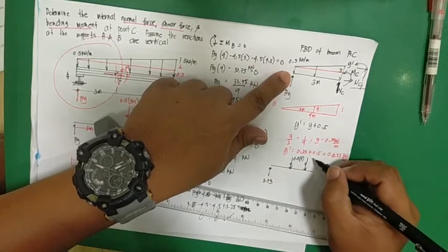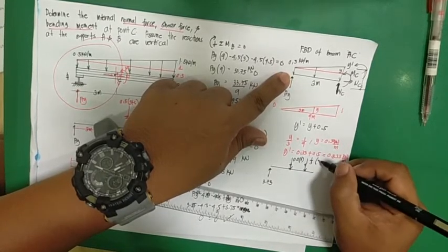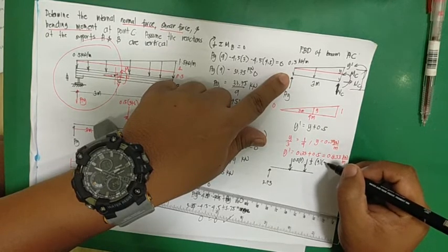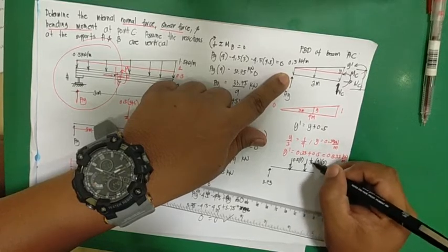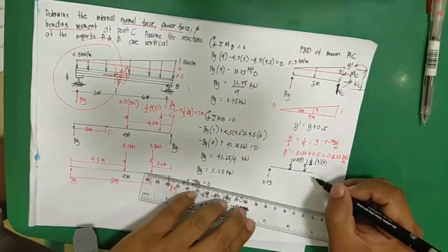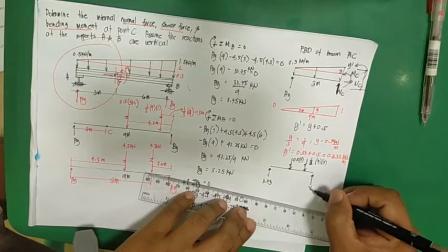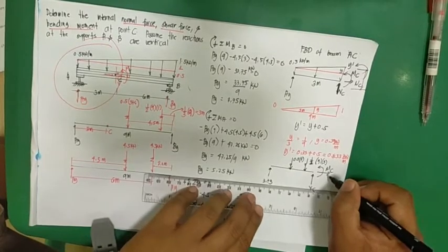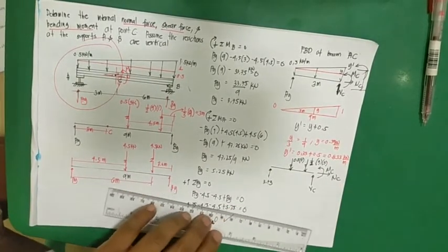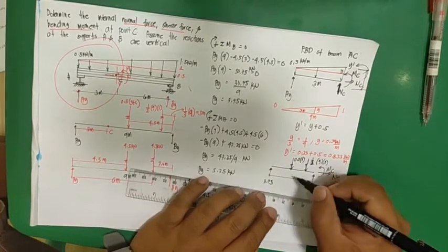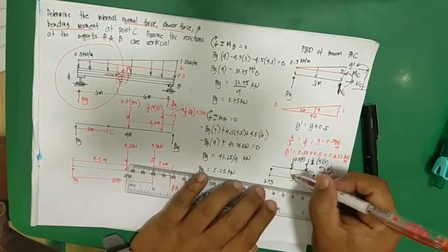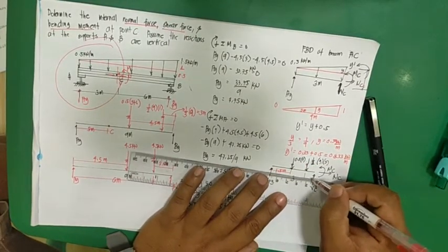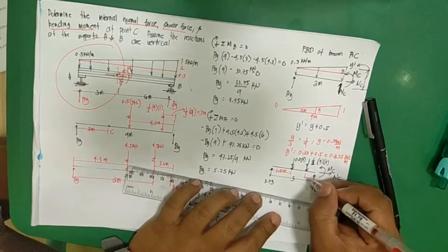The other one is 1/2 of y times 3. So this is BC, the moment at C, and you have the normal at C. The total length here is 3, but this one is located 1.5 meters, and this is located what? 1/3 of 3.